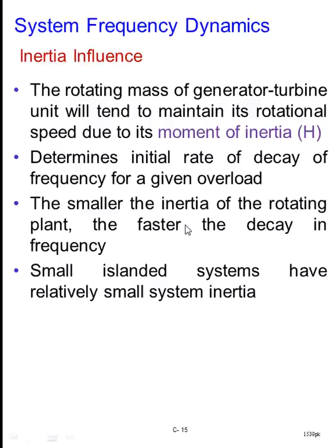The slope of the frequency change will not be that sharp. An isolated system has a smaller inertia, and thus the decay in the frequency is much sharper, as you can see in this slide.